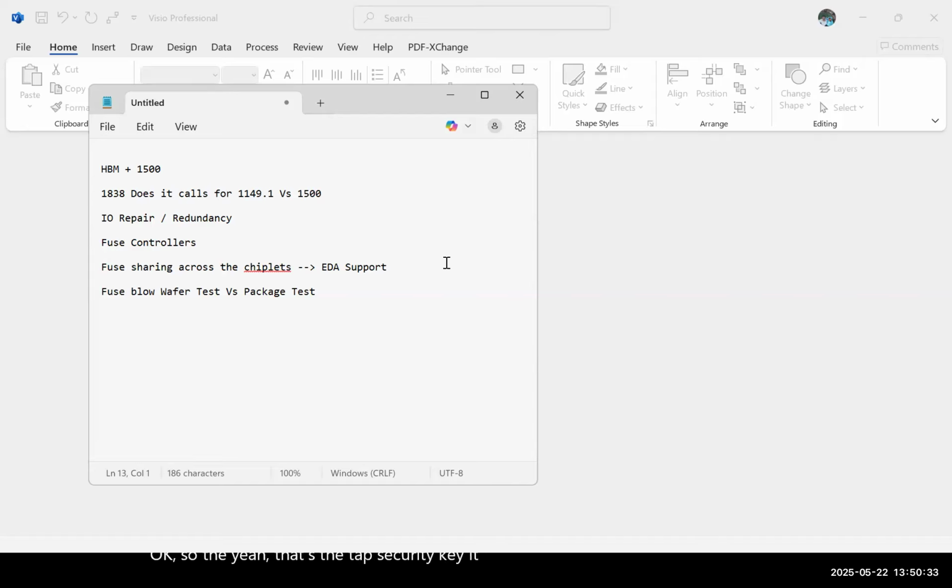That TAP security key comes in two places. Vikas pointed out one place, and then there is one more fuse, one more signature, where it can unlock the TAP. It can override that PTAP fuse in a factory setting, so you can give life to the PTAP access again. That will be useful for any of your RMA kind of debug. But for in-field test scenarios, this is again a challenging part, where end users want to run the DFT test. At that time they don't go through the PTAP, it is only for ATE purposes.